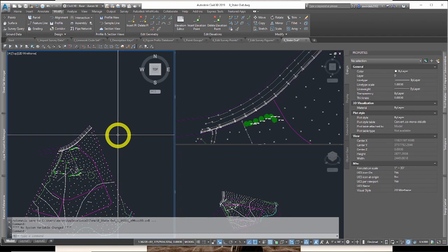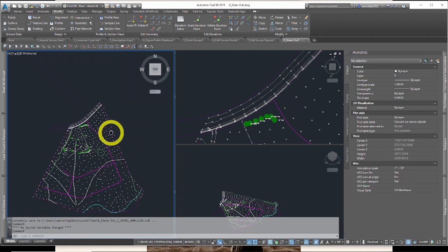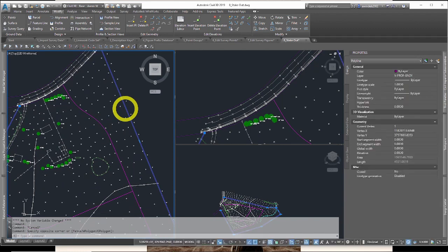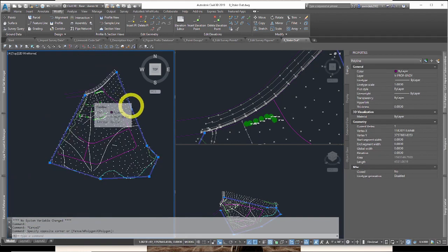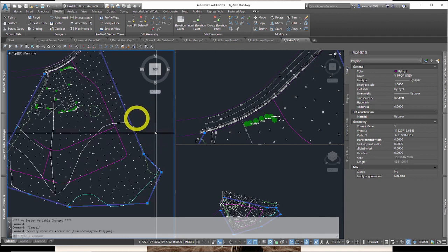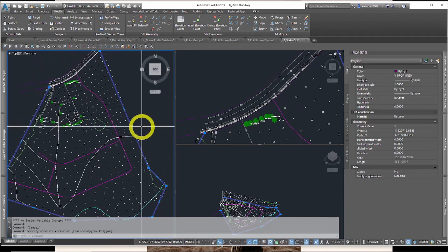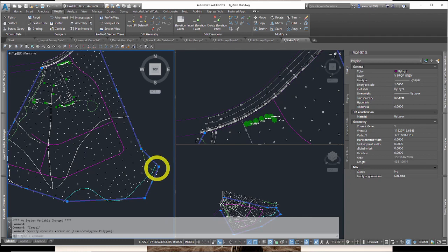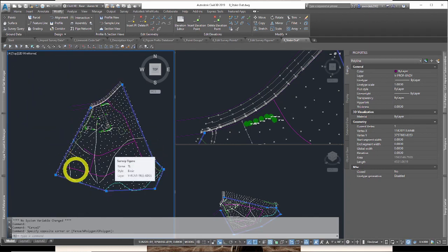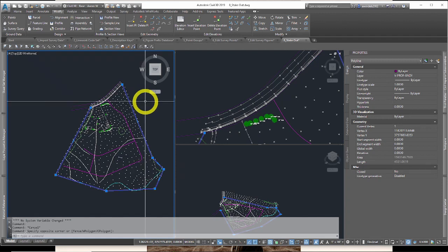Let's say you drew this whole boundary in this magenta based on an established survey record. You drafted it in with its bearings, distances, and exact real world coordinates, maybe in a local system, but real world distances and bearings, and you're missing some things. You need to go to the field now that you've drafted in these property lines, as many surveyors would call dry labbing, or you're calling out the boundary from record.